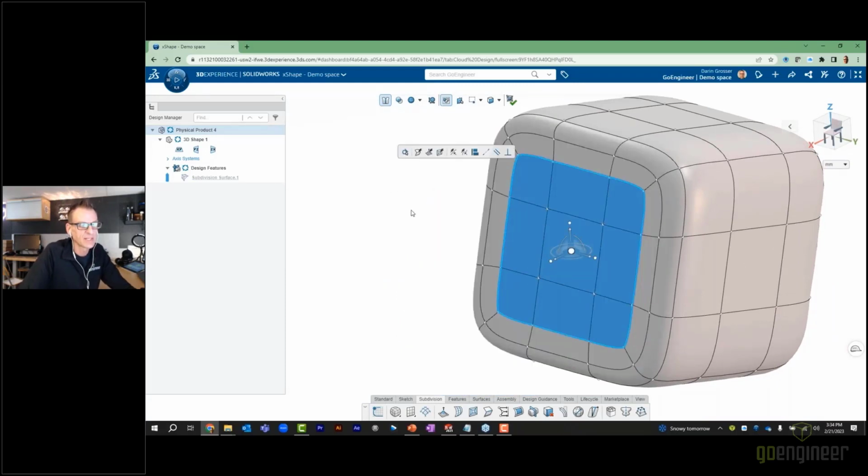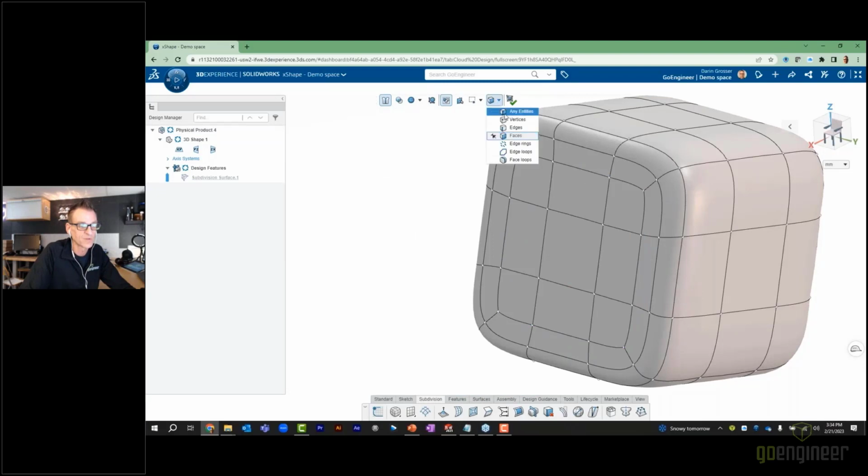So if I go ahead and select that, what I really want to do is control or emphasize how these edges work. So here's where I want to be able to pick anything. Let's go back to any edges. First, if I double click a loop, it selects the whole loop. That's very cool. Now it does that if it's tangent. Here I'm just going to turn this into what we call a crease. Now nothing's going to happen right now, but that's okay.